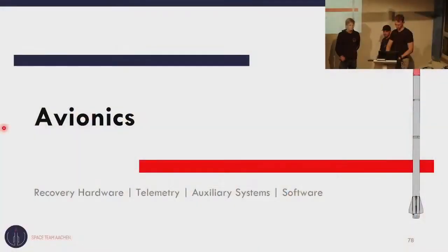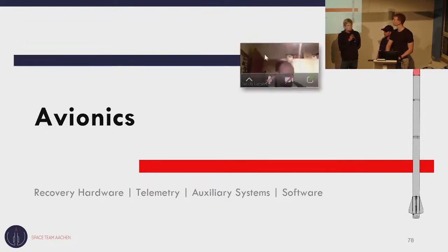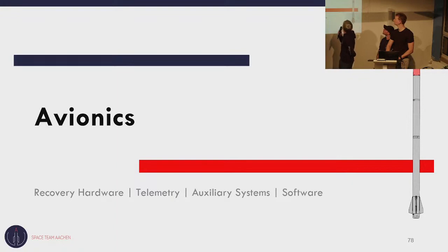I would strongly recommend that you map out the overcurrent thresholds on these devices and make sure that you have a safety factor of at least 2.5 on the current draw. Yeah, we will do that, and hopefully we will come back with results that show that our battery management systems are sufficient.